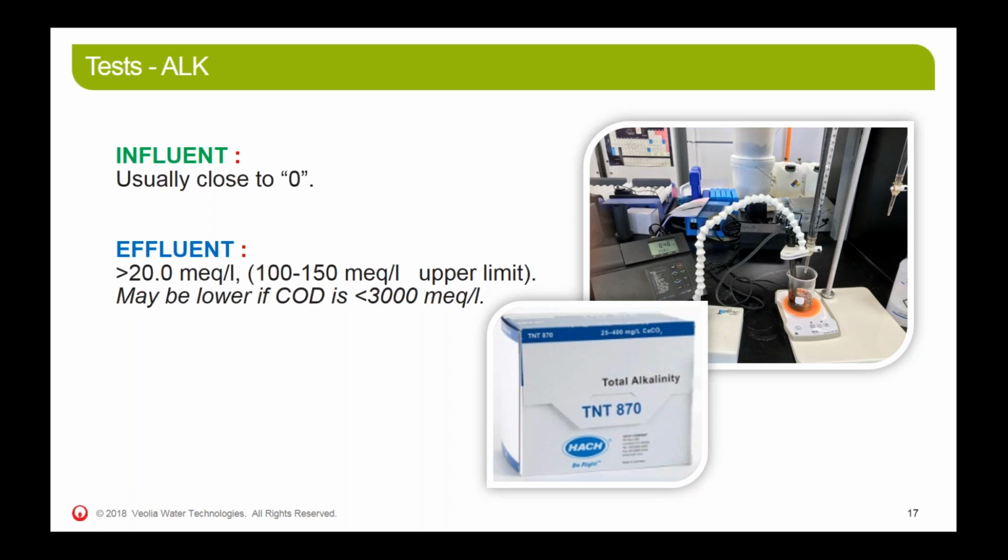This will ensure that if the system starts to get high VFA, the pH won't change, because before the pH changes, the VFA has to use up the alkalinity. It will be balanced by the alkalinity. So if you have like 20 milliequivalents of alkalinity and your VFA comes up, it'll be a while before the pH comes down. If you have a VFA problem and your pH goes down, it's a double whammy, and you don't want that.